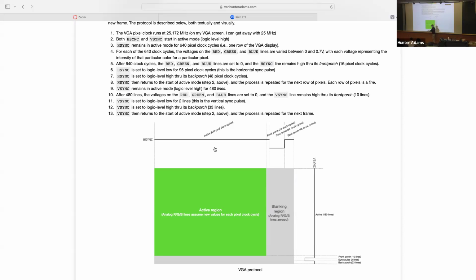Just by writing to that array, then in the background, a DMA channel comes in and moves through that array, grabs information out, and whisks it off to these PIO machines that are controlling the VGA screen, so that when you change the value at that index, the color that you asked for just appears at the right place on the VGA screen. And so to your application, writing to the VGA looks just like changing the value of an array.